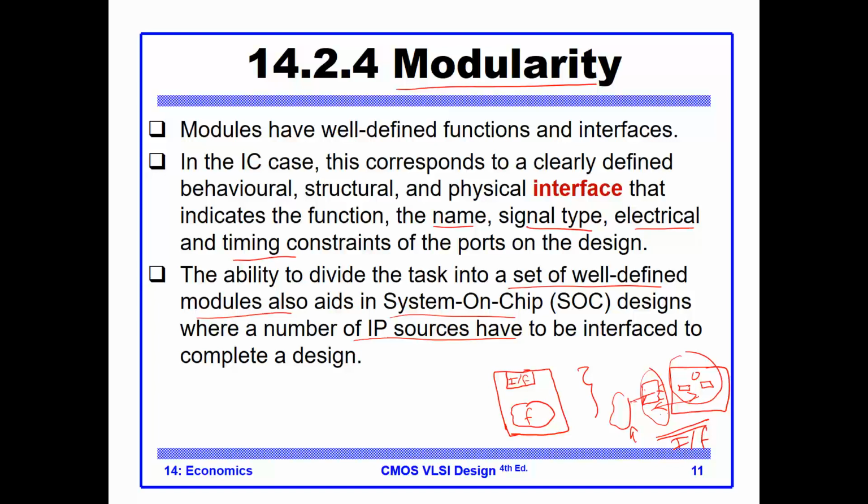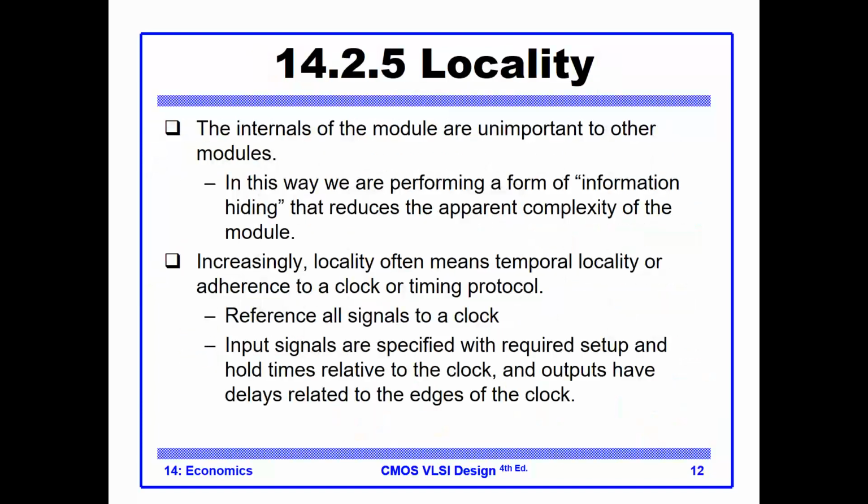Okay, one of the most common mistakes in hardware verification is that people will hook up hardware pieces with probably the same signals, but these signals could mean something slightly different from each other, and this creates a hardware bug because the definition of the interface is not accurately described in one of the interfaces. Now, locality. It really means that we hide the internal details of the module.